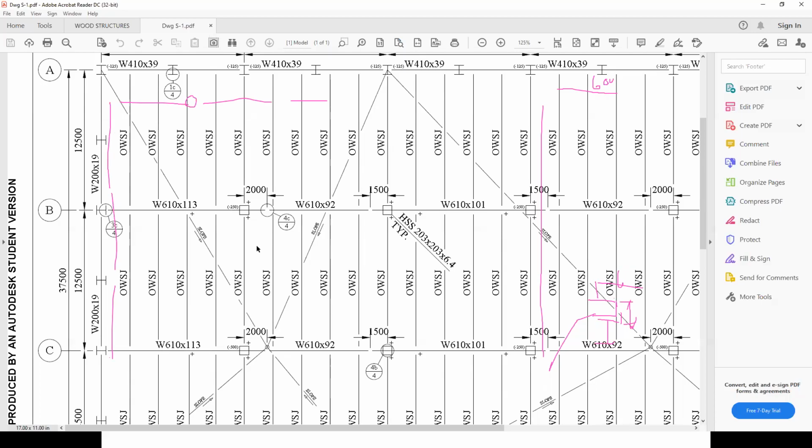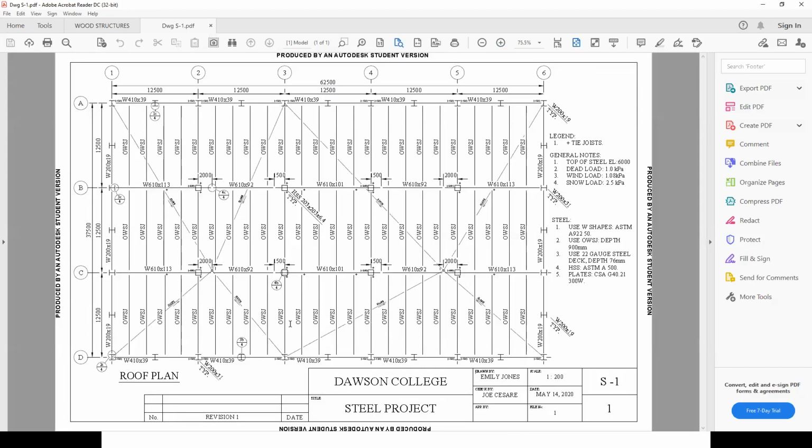So what you have to do is create in your steel structure the slopes that the architect is going to need to be able to drain his roof. And then when the fabricator is fabricating your steel, the steel detailer for the manufacturer will keep in mind to prepare all his shop drawings based on the information that you show him here. Okay, so that's okay. So clear, and let me go back. Okay, so that's what you see here. And then of course, don't forget, you would have to show where your cantilever is.